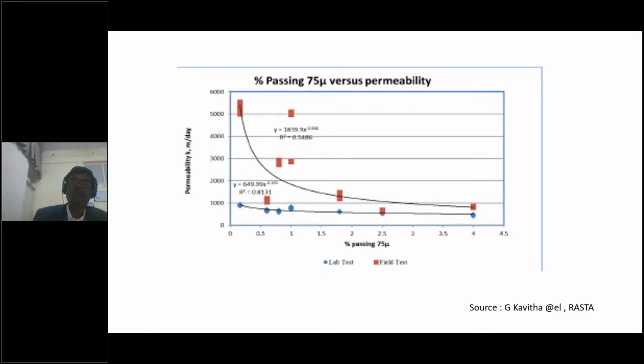The whole system fails. Whatever the best resources, the best design, the best management practiced during the production process, construction process, all will go waste if this layer does not perform. We have investigated, we have seen many major road projects have failed in the initial stages just because of poor material composition in the GSB. So this is very important.